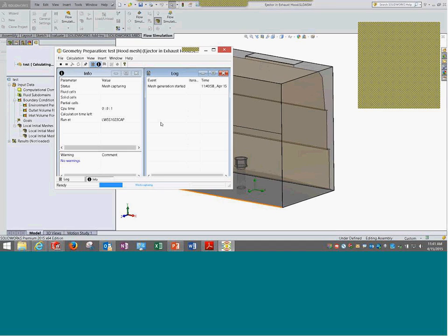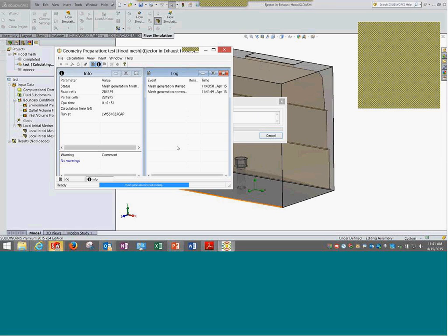While meshing, I would like to highlight. One, you saw the default initial mesh, that particular bar which is present, which can be used. Then you have some options in terms of the thickness, that is the minimum wall thickness gap and liquid gap. This is the second control that we have. The third control would be more absolute. Given a particular cross section or a plane, I can specify how many elements I want across the thickness.